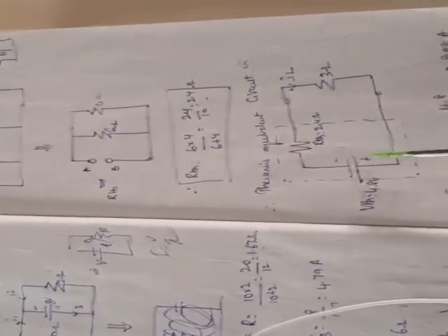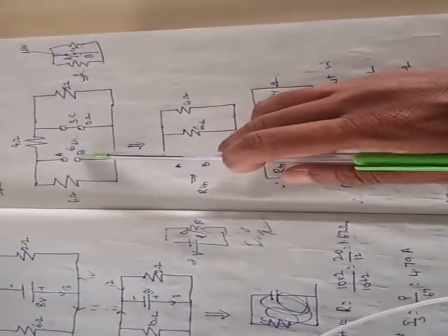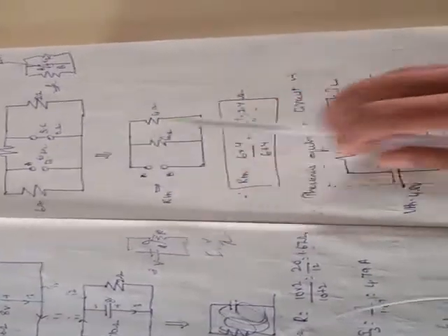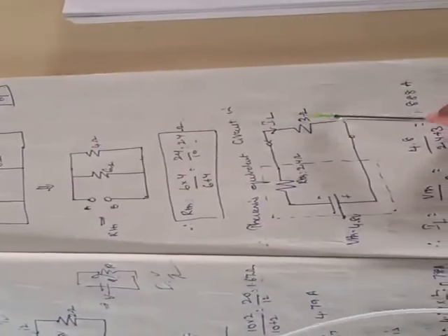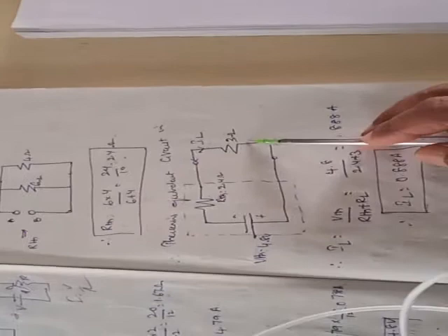This dotted line indicates a Thevenin equivalent circuit. So what is the open circuit resistor over here? That is nothing but load resistance. What is its value in the problem? It has been given as 3 ohms, right? You can observe here, 3 ohms is the open circuit resistance, so that is called the load resistance. Bring it over here and attach it to the circuit.